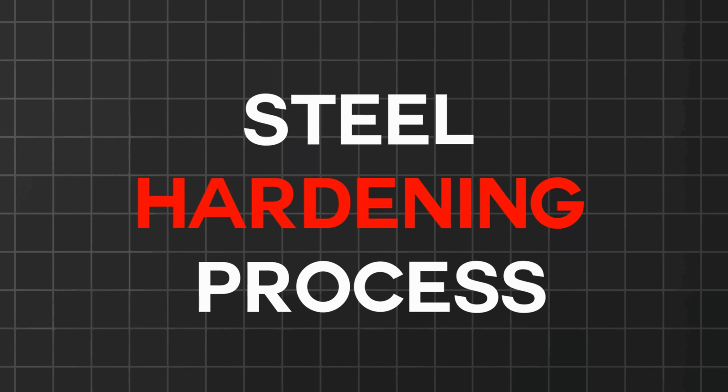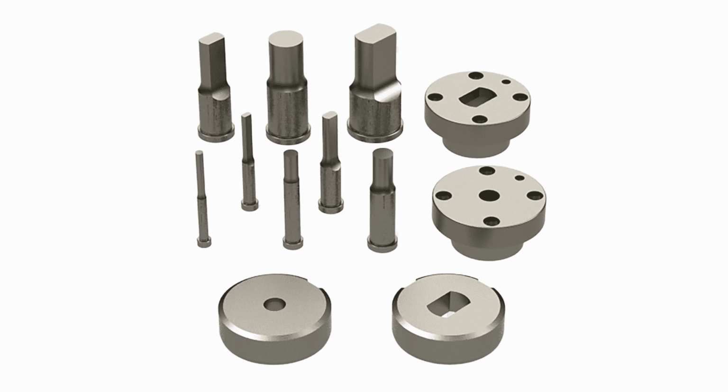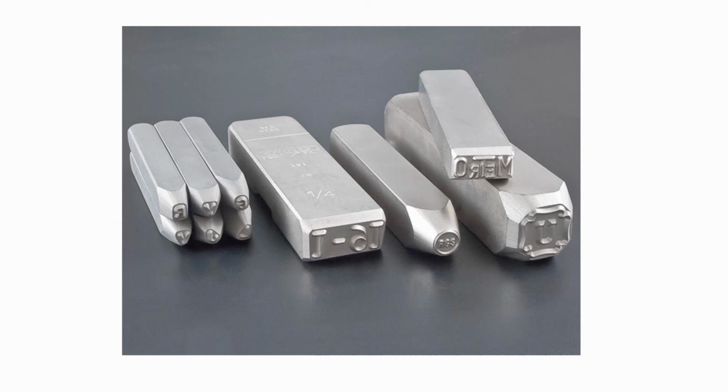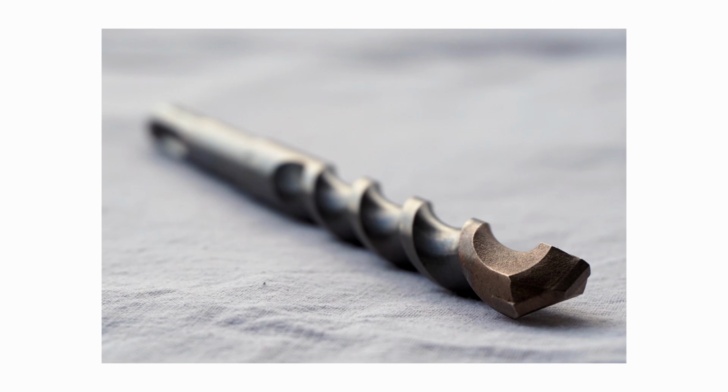As a mechanical engineer, especially as a design engineer, understanding the steel hardening process is extremely important because as a designer, it is our responsibility to specify the appropriate hardening method and the hardness value, HRC value, for the steel components in their manufacturing drawings, particularly for tooling components like punching tools, bending tools, flaring tools, clinching tools, riveting tools, marking tools, cutting tools like cutters, drills, and there are a lot more.